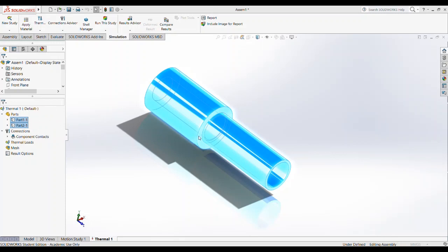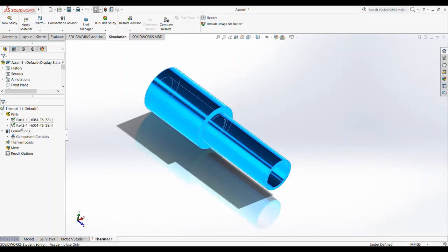Another word for it is automotive aluminum, and we use this for all our spacecraft. This is kind of the main one. There's other alloys if you want larger strength, but 6061 T6 is a good one. So you click that and hit apply, and you close. So now what it did is you could see it gave you a little check that you selected material.